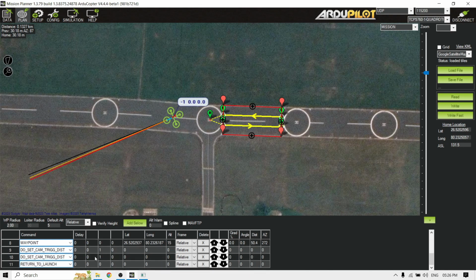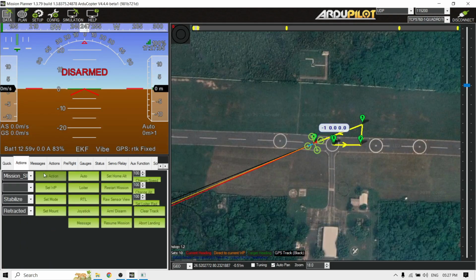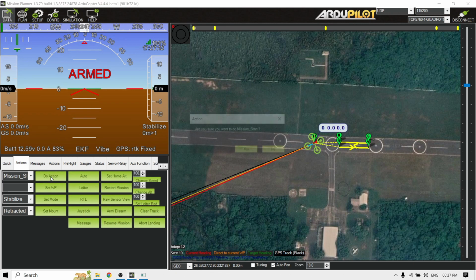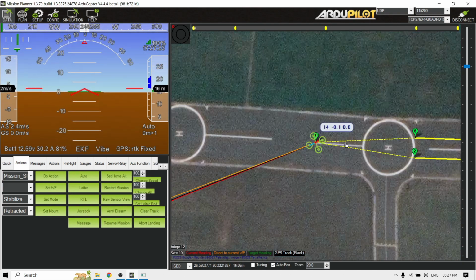You can see everything is auto created. What you need to do, come over here, get the action tab, be in stabilize mode. Robo Rose X, mode stabilize. Arm it. Robo Rose X Omni Tech Solutions drone armed. Robo Rose X, mode auto, and it's starting. It's taking off.